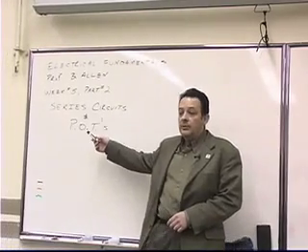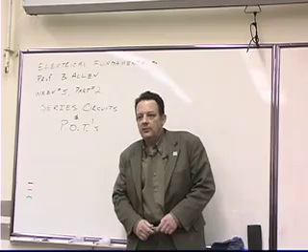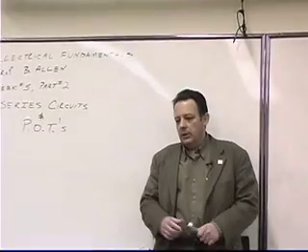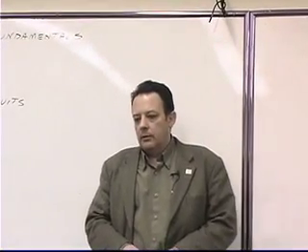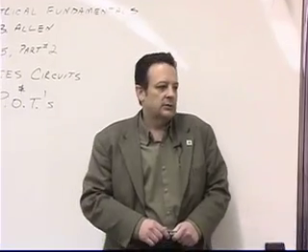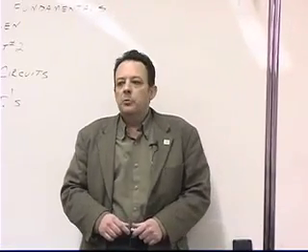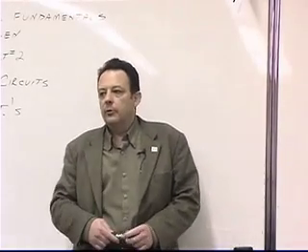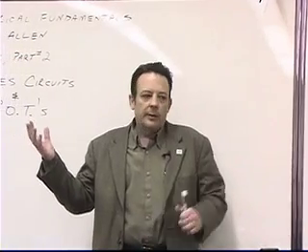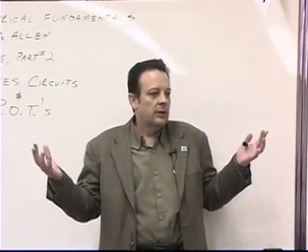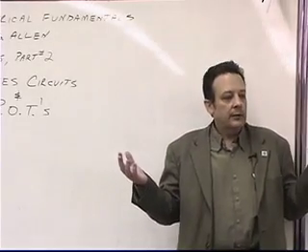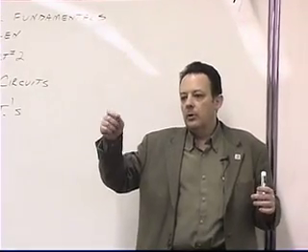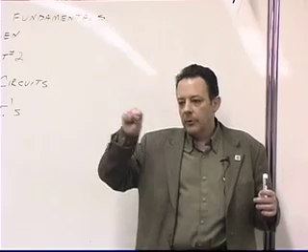But anyway, today is part 2 of week 5 for LTEC 213, and we're going to be discussing series circuits and potentiometers. The abbreviation for potentiometers is POTS. POTS are used extensively in all different aspects of electronics and electrical systems. In your book, when you read about variable resistors, or POTS, they'll sometimes be referred to as potentiometers and sometimes referred to as rheostats. Okay? They effectively do the same thing, and what that is they allow you to have a resistor that you can change by twisting a knob or moving a slide or doing something mechanical.